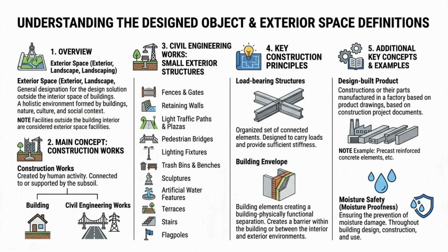Another essential concept is the building envelope. Building envelope elements create a physical and functional barrier either within the building or between the external and internal environments. Their purpose is to separate spaces, control environmental exchange, and contribute to the building's overall performance, especially in relation to energy efficiency and comfort. Design-built products are construction components or assemblies that are manufactured in the factory according to special product drawings, which are based on the building project documentation. Precast reinforced concrete elements are a typical example of the design-build product.